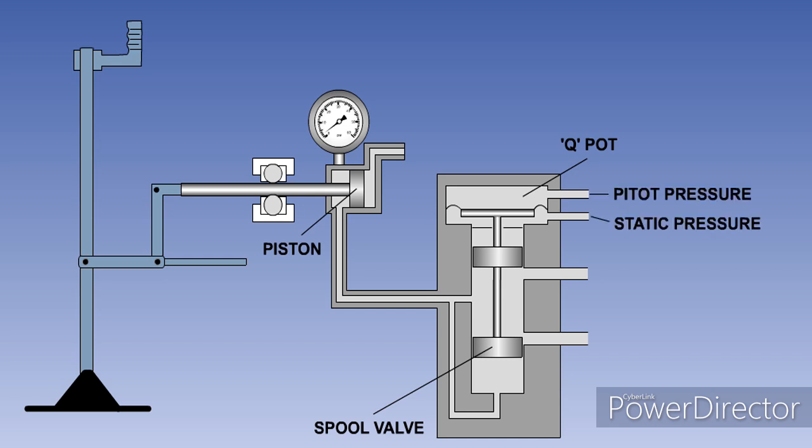With the forward movement of the aircraft, pitot pressure is fed to the upper chamber of the Q-pot section of the unit, pushing down the diaphragm. The diaphragm is connected to a spool-type selector valve, so that the downward movement of the diaphragm opens the hydraulic pressure port and partially closes off the return port. Hydraulic fluid emitted to the unit will then pass to the forward side of the piston. The fluid also passes through a narrow channel to the underside of the spool valve to dampen its downward movement.